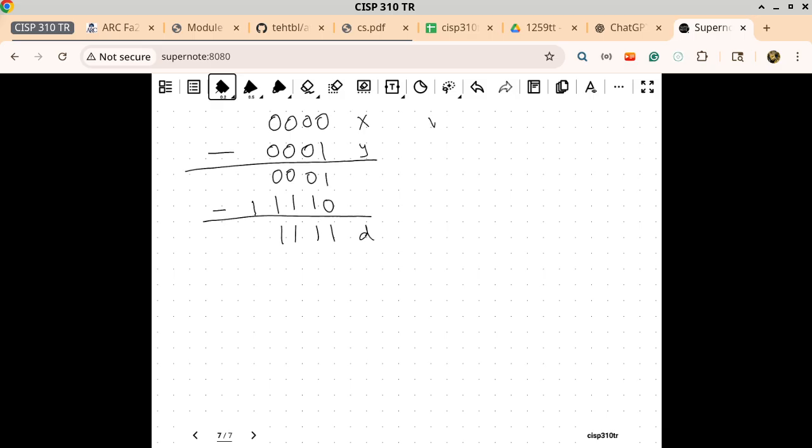So we want to go like, okay, what is VS x4? I think this one is pretty easy. 0. Very good. And what about VS y4? That's also really easy. It's just 1, right? So 0 is less than 1 is true, right? But we look at the sign flag of the difference, it is also 1. Okay, so this one has d3 being a 1 when x is in fact less than y. We flip the order of those two.